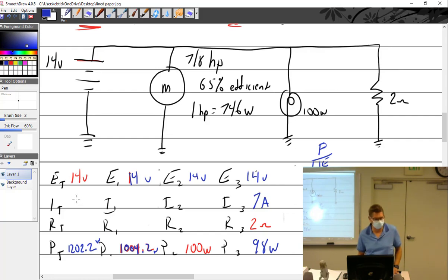Yeah, I screwed up on the motor stuff, my total and the motor. You guys following along? I feel like I'm all by myself suddenly. What are we working on right now? Solving for current on the total. What do we get? It's P, I, E. I equals P divided by E: 85.87 amps.